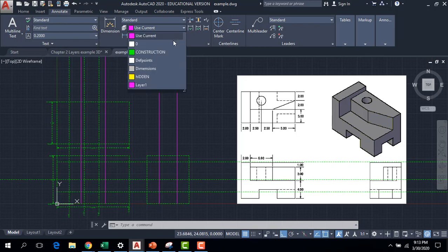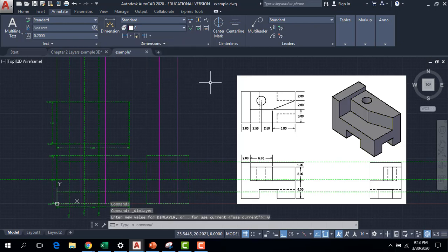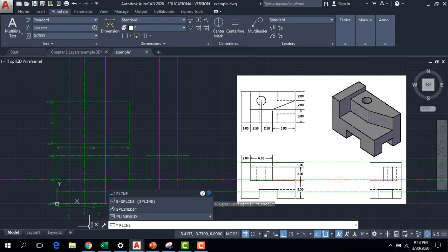I'm now going to switch over to our main outline layer and just use snapping to walk around the outline of this thing. While you're doing this, really make sure that you don't draw two different lines on top of one another. It makes it really hard to extrude and tell what's going on. So keep track of things and don't redraw the same area more than one time.